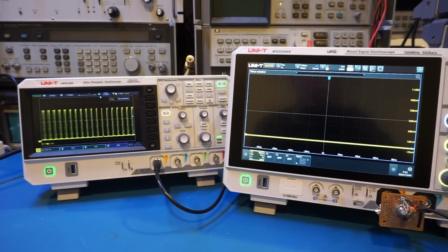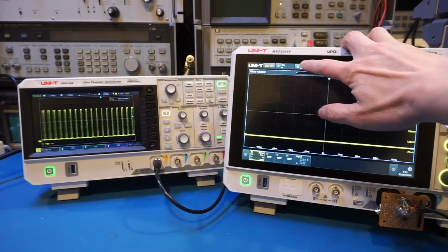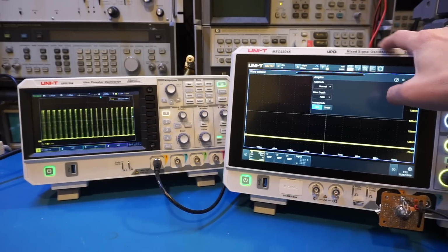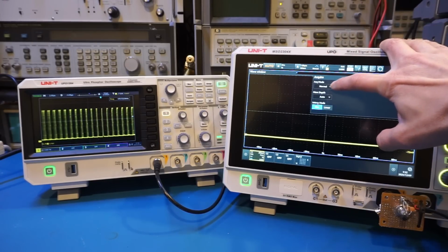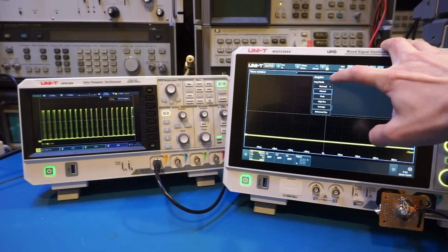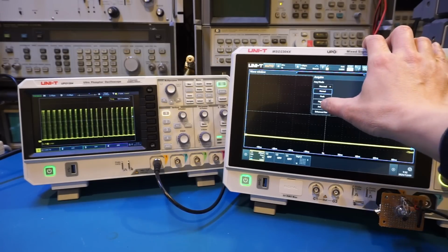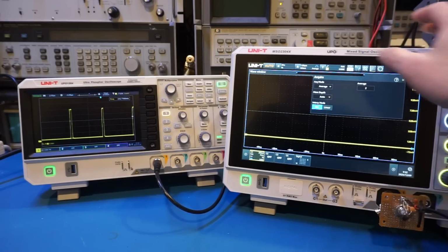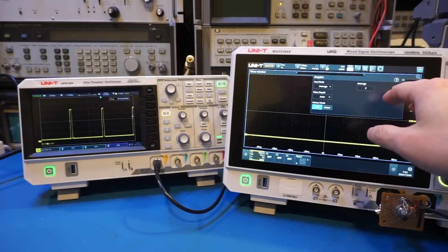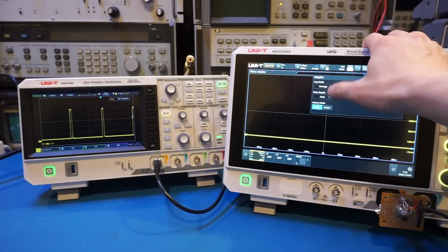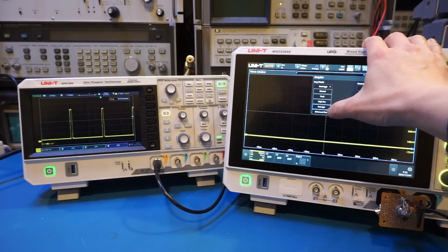Now, as I mentioned earlier, the triggering rate is actually affected by multiple settings. So let's actually take a look here. If I go to acquisition, for example, right now the acquisition mode is normal. And I mentioned if we change it to, let's say, average, actually this one will lower it. Yep, because we're actually averaging 2 per waveform. And let's change it to enhanced resolution.